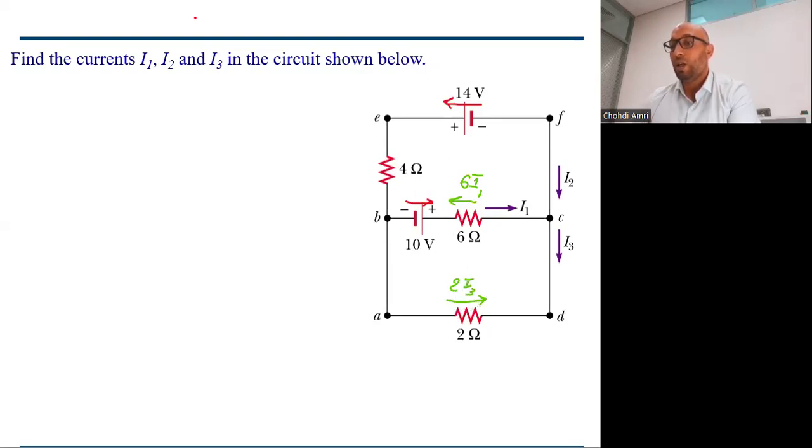We have again here the current going clockwise. So this is the current I2. The current is upward, so the potential difference will be downward, and it's equal to the 4 ohm resistance multiplied by the current going through this resistor, 4I2. Okay, so we are done with the first step. Draw the circuit diagram.